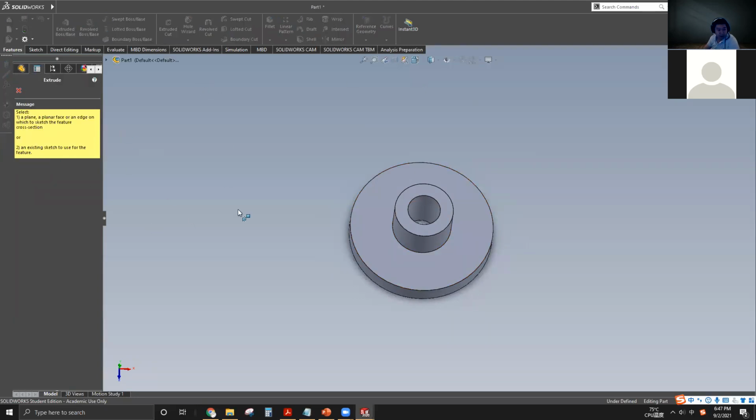It was an extrude cut before, even though we're supposed to use Hole Wizard, but the Hole Wizard has the built-in specs of those ANSI, ASME, those common hole specs, and even threaded, all this other features in it. But for now, let's just use the extrude cut to make holes, because it will be easier for you. We're going to have a separate section to go over Hole Wizard.